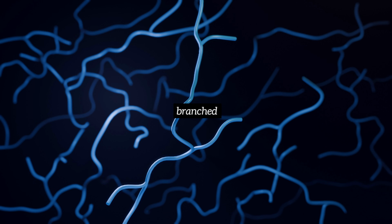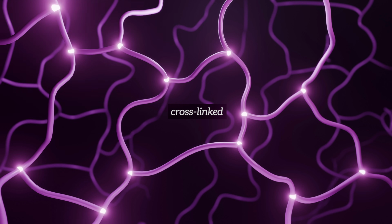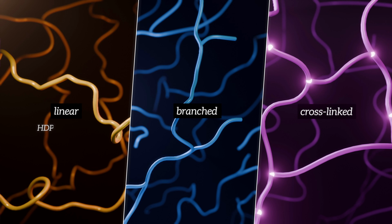And in cross-linked arrangements, strong covalent bonds are formed between different polymer chains. This creates a rigid three-dimensional network that's very structurally different to the linear or branched arrangements. High-density polyethylene and PVC are examples of polymers with linear structures. Low-density polyethylene has a branched structure, and vulcanized rubbers have a cross-linked structure, as we'll see in more detail later.